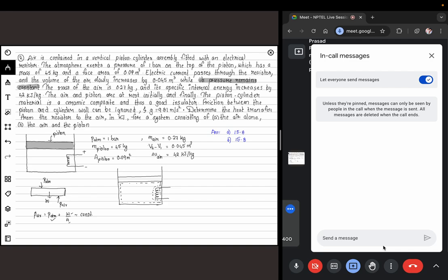And then you have something like this. So everything except the resistor is my system. So the resistor is outside my system boundary. So across the resistor there won't be any mass transfer, so I can consider this as my boundary. So my system is defined. So this is case A. So I am considering only the air inside this as my system.